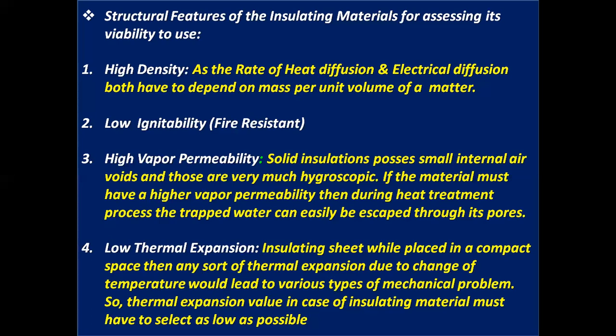Number two, low ignitability, that is fire resistant. Number three, high vapor permeability. Solid insulations possess small internal air voids, and those are very much hygroscopic. If the material must have a higher vapor permeability, then during heat treatment process, the trapped water can easily escape through its pores.